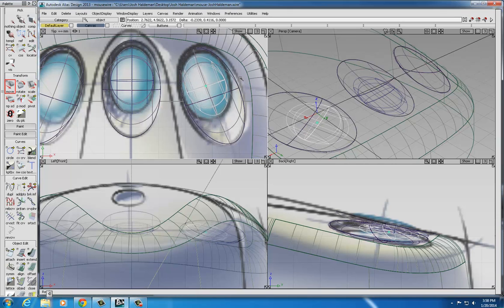You can tell when you look at this thing that it's a little off from where the reference is. And a part of that's because of where we placed our housing and how we oriented it. Use your best judgment here. Line it up where you think it'll look correct, and base it on where the geometry is, not necessarily where the reference image is. At this point, when you get this far along, it's important to allow for that. Once you get it pretty close and you're fairly happy with the results, again in the top view, then check it in the front and the side, or in the perspective and the side views.